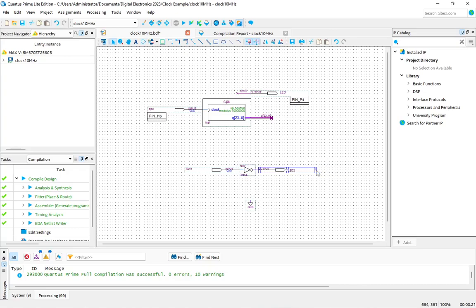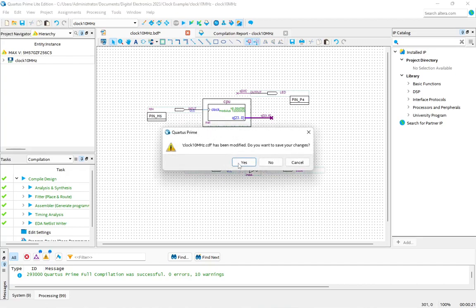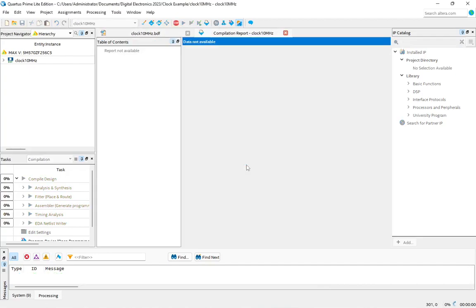So this switch is going to control this LED. Since by default they're on, I want to send a 0 to it, so when I press the button, it's going to go high. And then build that.